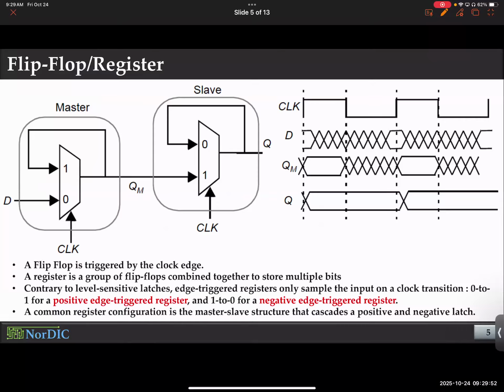Now let's see how this circuit responds when the input and output change. Imagine this is your actual input, data D. Since these latches are connected, the second one does not have any dedicated external input. It is being driven by the output of the first latch. Does that make sense? You don't really control the input anymore. For the second latch, the input is essentially the output of the first latch. So they are, of course, linked with each other.